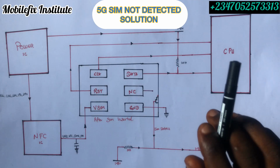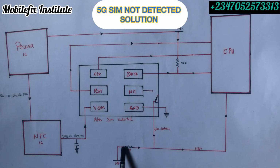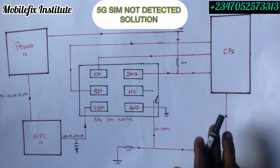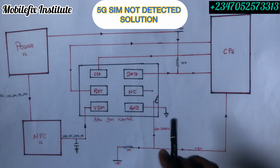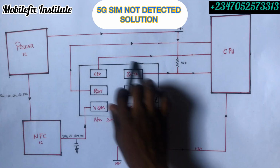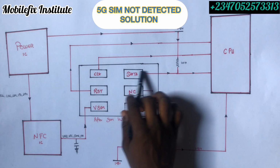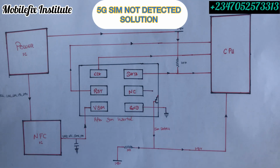The only place that you will get voltage without inserting your SIM is on this side of the 10K resistor, this detection line. This side you will get your voltage, this 1.8, without inserting your SIM, but you won't get voltage on this side. Only after you insert your SIM, that's when you get voltage on this side. So all the rest of the voltages that you will require, these data voltages and this NFC voltage, you have to insert your SIM and your phone is switched on.